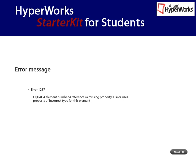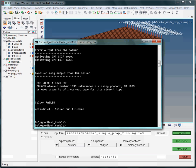This error message tells us that some elements are missing property information. Again, I would check everything related to properties. The error message is quite different than the others we have seen so far. See Quad 4 element number 1633 references a missing property. My 2 recommended debugging steps: first, check the property, and second, check whether the property is assigned to the elements.